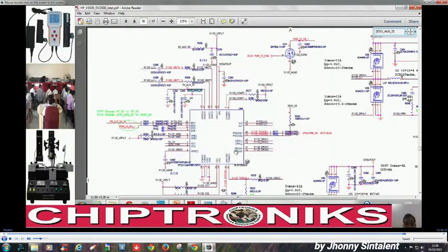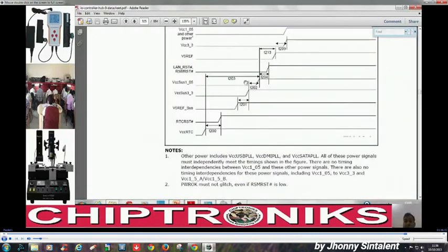Now you come back over here. We had already discussed this 3 volt 5 volt regulator in earlier classes. What I did was, I did not start with testing adapter voltages and then measuring 3 volt over here. I started with the sequence that is mentioned in the data sheet. And what is the sequence mentioned? Start with VCC RTC.